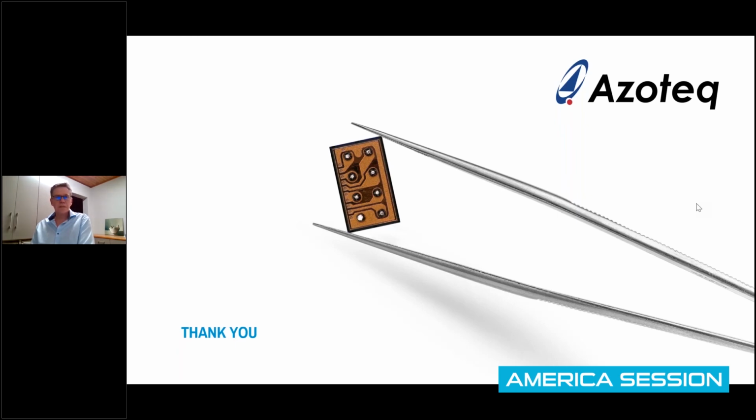Whereas capacitive sensing does not require any deflection of the top surface, inductive sensing does require a small amount of deflection. But if you are employing it in something like a plastic housing, or you have a plastic front cover, the perceived pressure from the user can be such that it feels the same as capacitive, even though there's a small amount of deflection behind it.